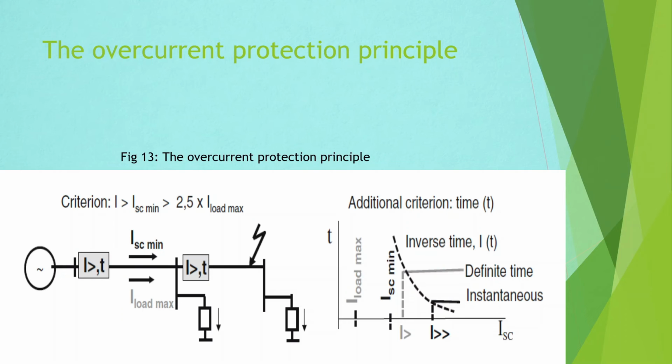The inverse time overcurrent protection trips in accordance with a time delay depending on the short circuit current, for the application of meshed HV networks. The overcurrent protection is supplemented by the specific directional criteria and needs the input of the phase voltage for processing. The busbars are the most sensitive components in the network.